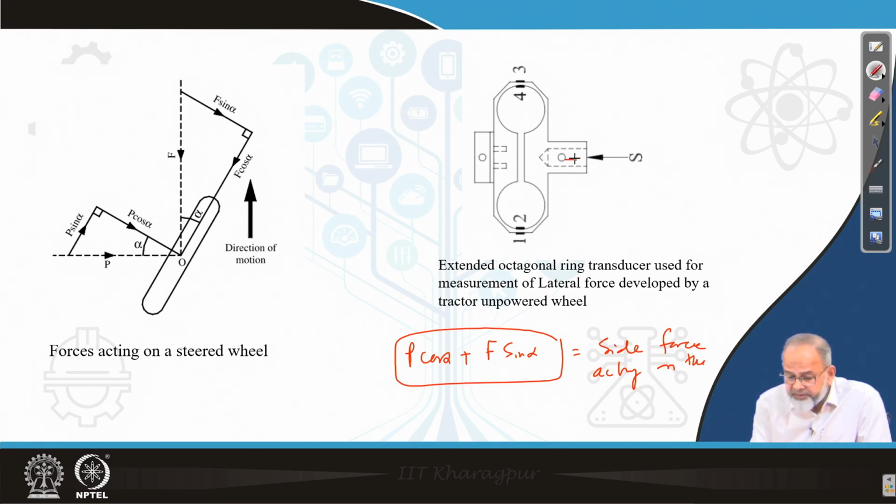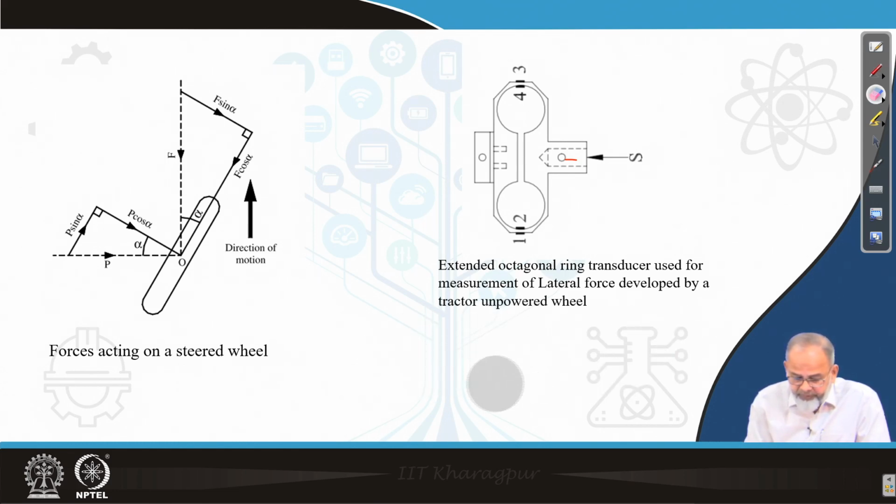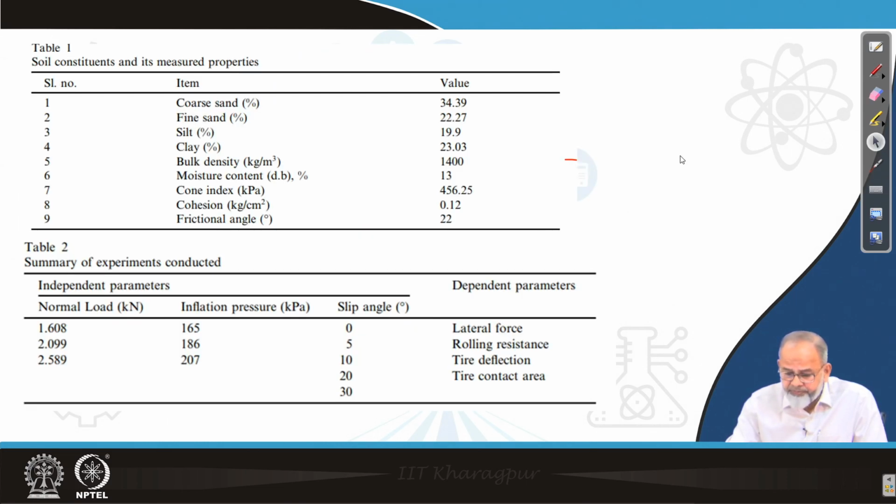The axle is inserted in this bush, and one end is mounted on the frame so that you can easily change the position of the axle, and thereby change the slip angle. Now, once we know the arrangement, we look at the parameters we try to vary.